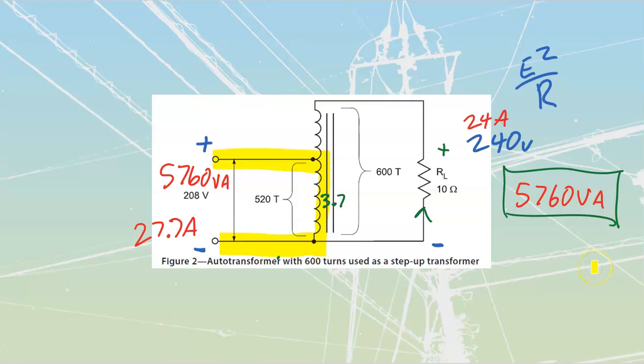What I would need is a transformer that is built with wire sizing, standalone. If it was an isolation transformer, it would have to be something that's a 769 or a 770 VA type of transformer. We're not going to usually have to calculate that, by the way. This is just practice because we just did this in the previous one. Same with the current analysis. We just did this in the previous one, and it helps us to sort out what's happening inside of our transformer.